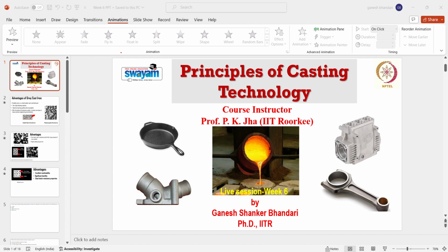Smelting is defined as slag plus melting operations, and during smelting operations we go with two types of slag practices: first, basic slag practice, and second, acidic slag practice. That will depend on the material that is going to report into the slag. If we are talking about phosphorus, it will form basic slag, and if we are going with the slag formation of sulfur, it will form acidic slag material.